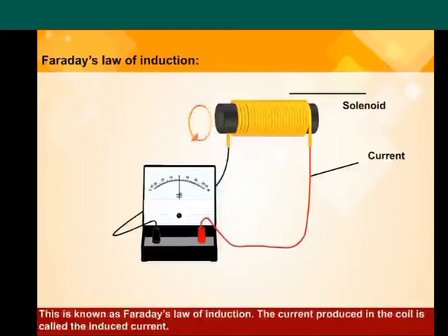What will be required to make a DC generator? The DC does not change the direction in the external circuit. To achieve this, a split ring is fixed on the axle like the split ring used in an electric motor. Because of this arrangement, the branch of the coil going upwards is always in contact with one brush and the branch going downwards is always in contact with the other brush. Hence, the current flows in one direction in the external circuit. This is why the generator is called a DC generator.